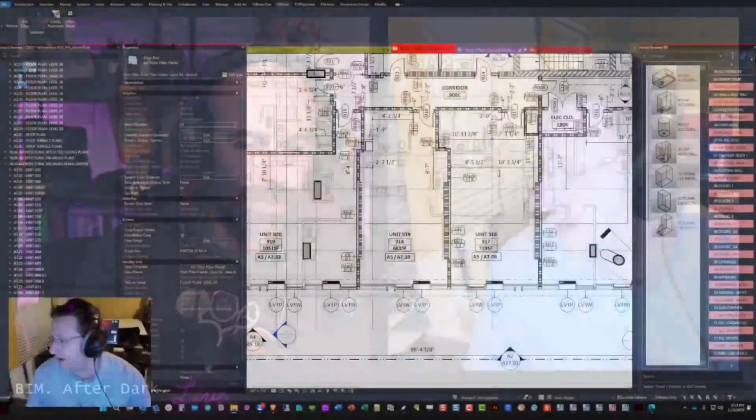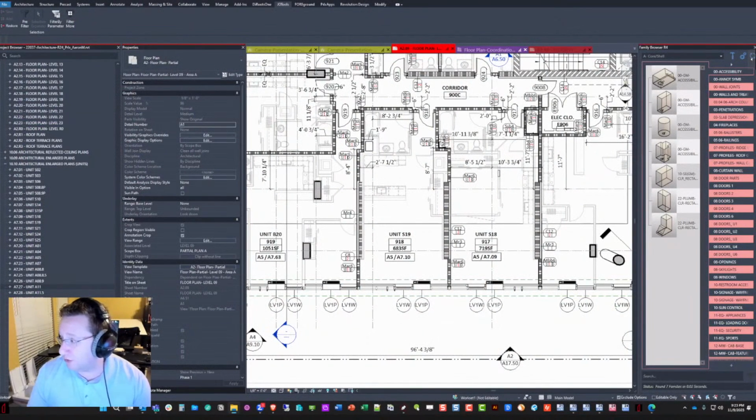I think you have to go to finished face, and ideally expand from the finished face. That would be your model line. If the wall needs to get thicker and encroach more on the units, then for me that is a different unit. Jeff, we actually worked with a contractor and remodeled all of the head walls, because the patient rooms were elevated as being typical, and then we started to look, and some were fire rated walls, some were different stud thicknesses, and we're like, that's all supposed to be prefab head walls. So we ended up remodeling it. We do it all the time, unfortunately.